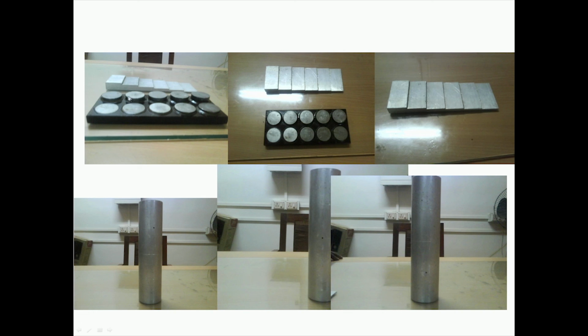Similarly, here also these blocks have different heights or different thicknesses. So, this also can be used to calibrate the instrument for distance, because then for each of these you can collect the back wall signal itself, and that can be used to calibrate the instrument for distance.